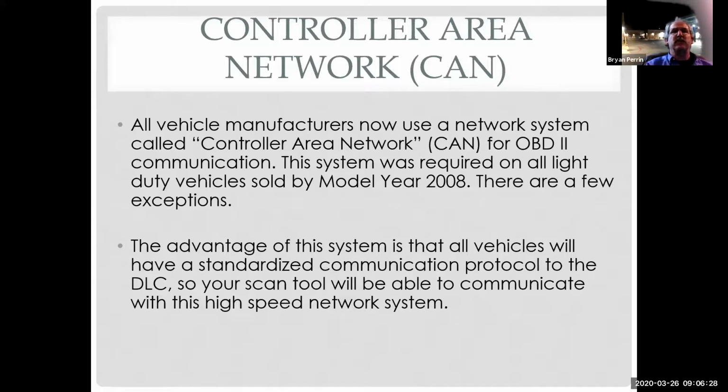The advantage of the system is that all vehicles will have a standardized communication protocol to the DLC. So your scan tool will be able to communicate with this high-speed network system. So this is big. We see a lot more bidirectional controls, a lot more data because the system works a lot faster than the older networks did. So we can move a lot more information quickly.